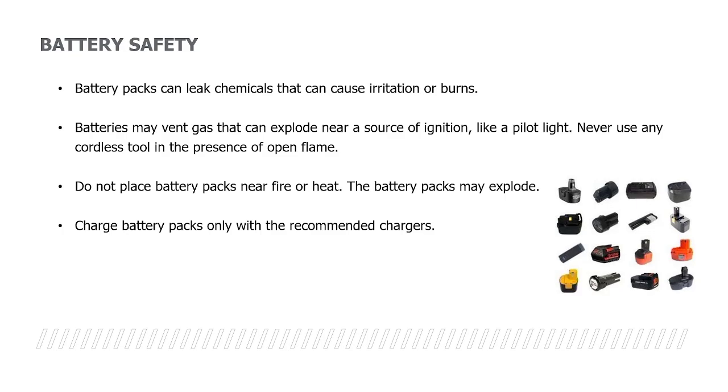The battery safety, once again: battery packs can leak chemicals that can cause irritation and burns. Batteries may also vent gases that can explode near explosive environments. A good example of that would be a pilot light. You never use any cordless tool in the presence of an open flame. And the other thing too is that battery packs may explode. Charge battery packs only with the recommended chargers. Whatever charger that particular battery came with, that is the charger you need to use to charge that battery, because the charger and the battery were designed to work together by the manufacturer.